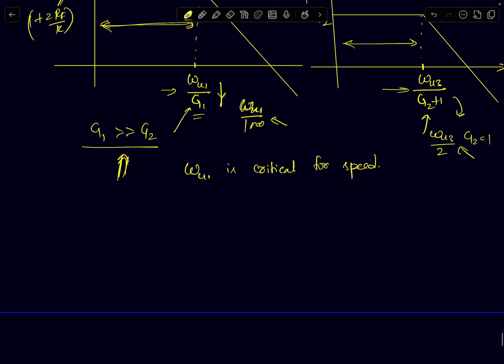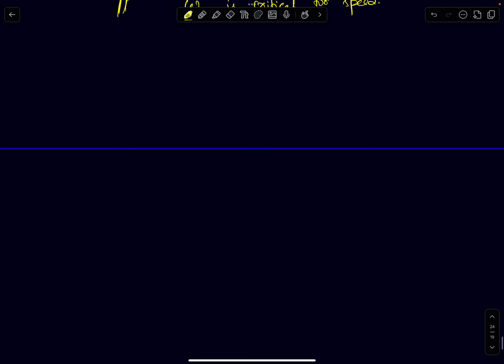To summarize, we have discussed the basics of instrumentation amplifiers, the construction of an instrumentation amplifier, and how to arrive at its structure. Then we saw data sheets of some popularly available instrumentation amplifiers in the market. Very briefly, we spoke about applications of instrumentation amplifiers. They serve as differential amplifiers which can amplify weak differential signals in the presence of strong common mode noise.